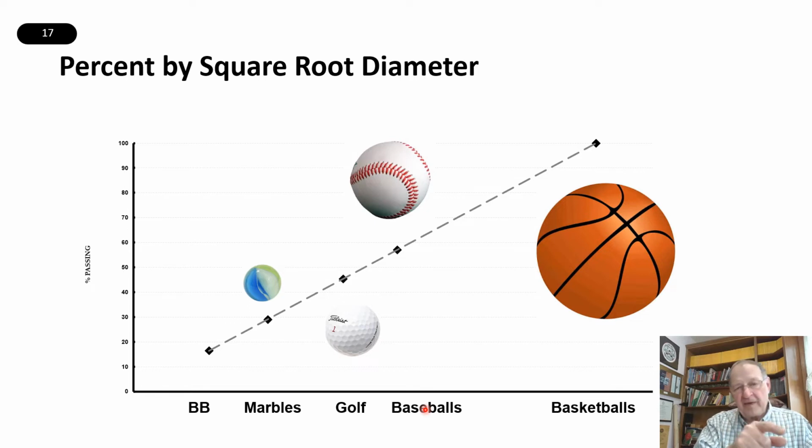And they found that if they made a plot kind of like this one, but instead of plotting the percent smaller than the half inch against the square root of the diameter, or the diameter raised to the 0.5 power, it actually worked better, because rocks are not balls, with the diameter of the rocks raised to the 0.45 power, and hence the origins of what is referred to as a 45 power chart.